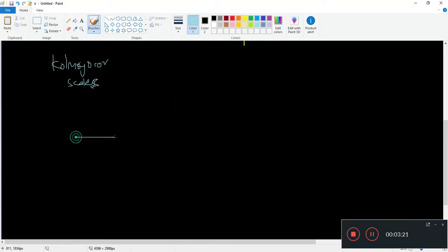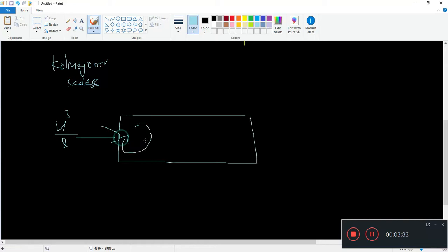Remember, we did it through energy balance. We had characteristic kinetic energy input determined by U cubed over L, and then it cascades into eddies, and the eddies break up and get smaller and smaller, until at the smallest scale the main means of dissipation is viscosity, because the smallest eddies don't break up into smaller eddies anymore.